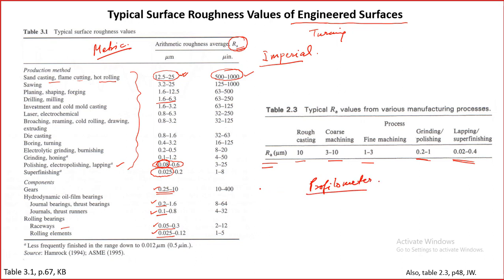So this is the surface profilometer, we call it, and you might know that it works on the principle of a stylus that moves. The stylus has a sharp tip, which is a diamond tip here, and this stylus will follow this path. Obviously this stylus cannot go deep inside, because the angle of this valley may be smaller than the angle of the tip, so it cannot go in, it will just follow like this.